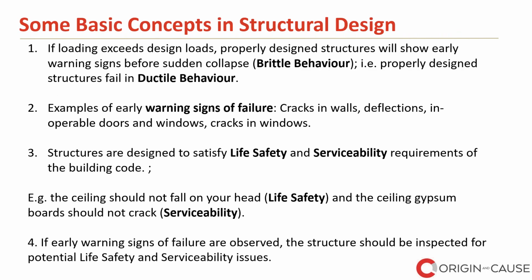But now, I want to talk about some basic concepts in structural design. A structure is designed to carry the design loads that are specified in the building codes. If the loading exceeds those design loads, a properly designed structure will show early warning signs before sudden collapse.